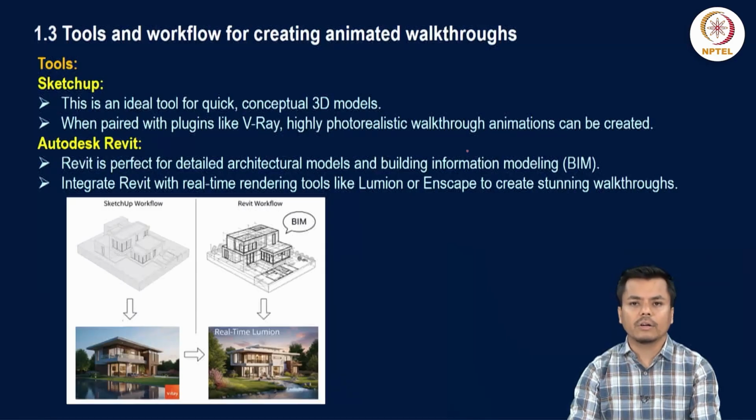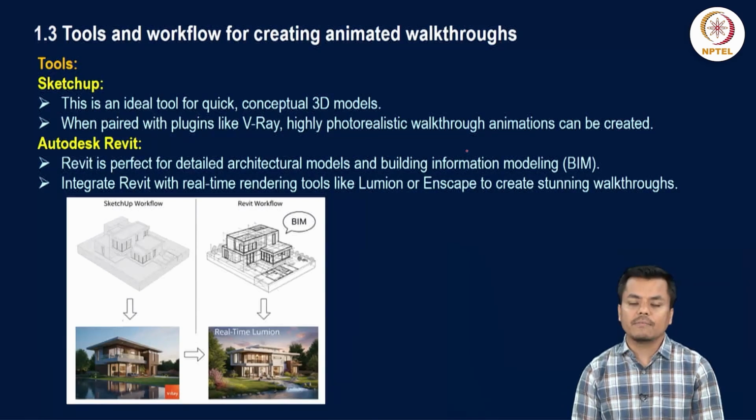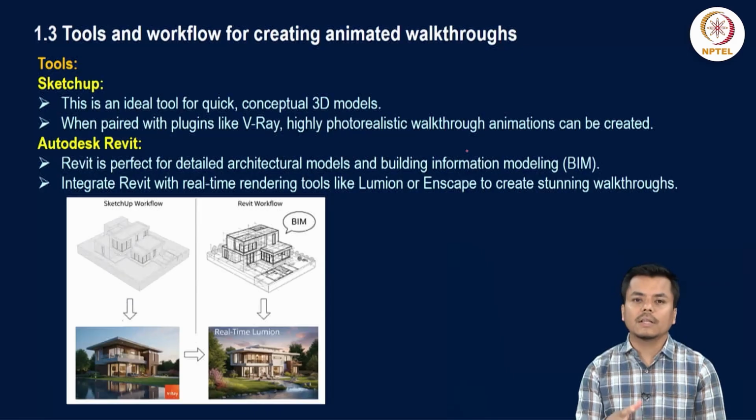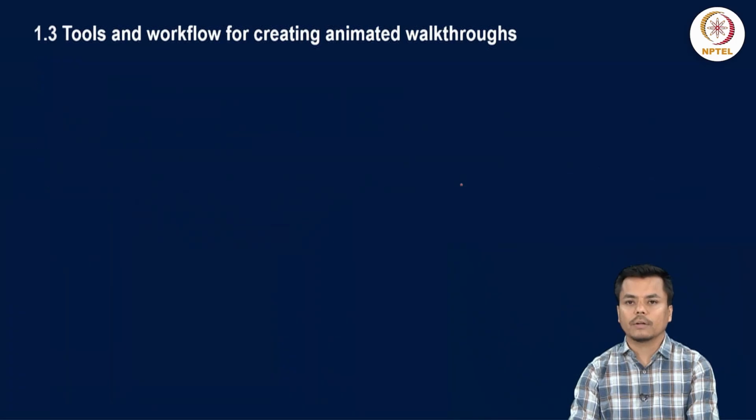The next is Autodesk Revit, because you have already prepared your model there, so you can use the same feature, just position the camera accordingly and then start creating the video in Autodesk Revit. It integrates Revit with real-time rendering tools like Lumion or Enscape, and then you are able to produce walkthroughs through the software.